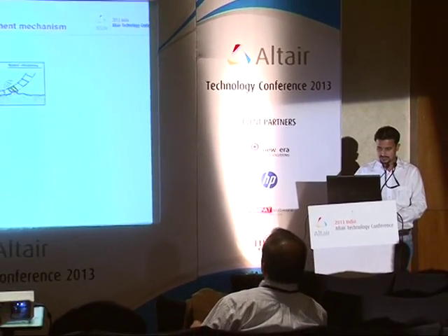Tire noise generation has various mechanisms. Stick-slip: when the tire comes into contact, several points want to come into contact, and several points which are already in contact want to come out of contact. This constant coming out of and going into contact generates a particular noise. And adhesion stick-snap: when a particular tread part wants to lose road contact, the adhesion forces try to bring it back to contact. This also causes a noise.